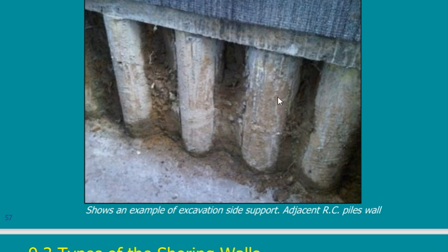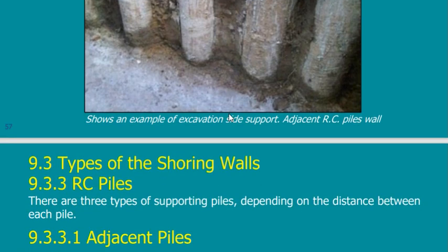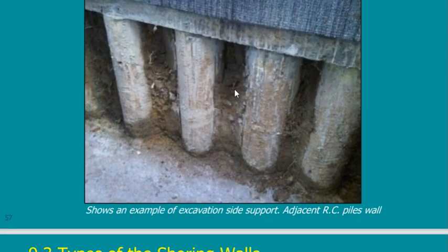It is not a big deal, because if you look closely at this soil, you will find it is a little bit clayey, so it can stand as it is. Why am I leaving this gap? To reduce the amount of money that I'm paying. Instead of using 100 piles, I may use 70. So I just added spaces that can carry themselves without the use of piles.